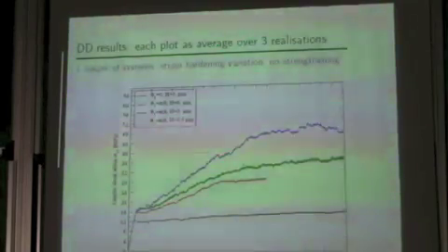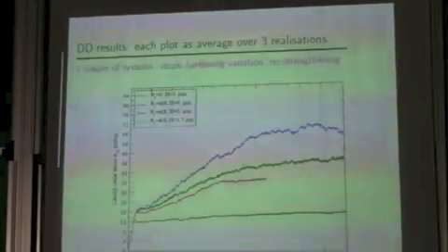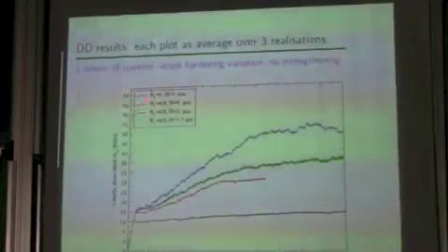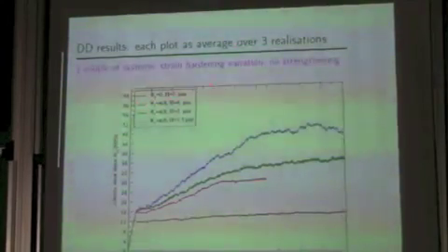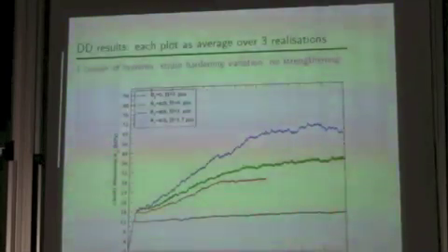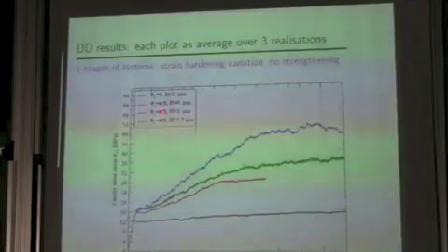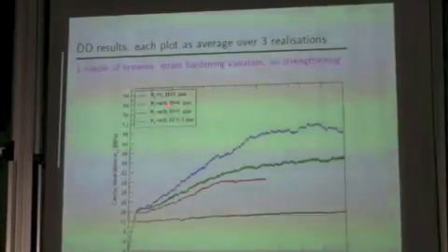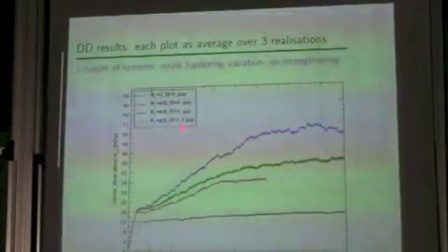These results are for just one couple of systems, and the black curve is for the system oriented like the shear direction. So in this curve you can measure kind of the self-hardening of the slip system, and the other 3 curves are related to couples inclined by pi/8, and they are related to 3 different samples.